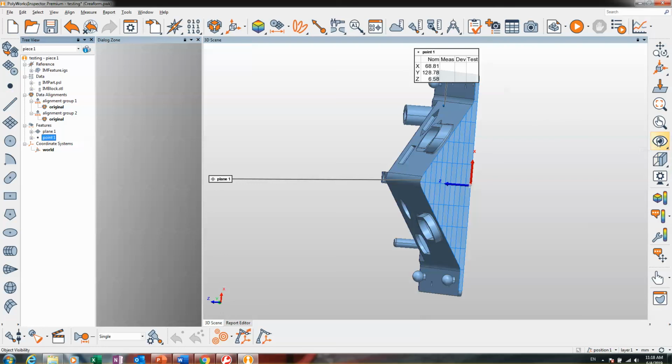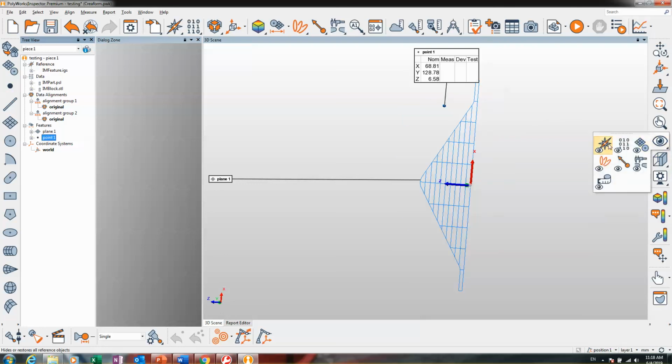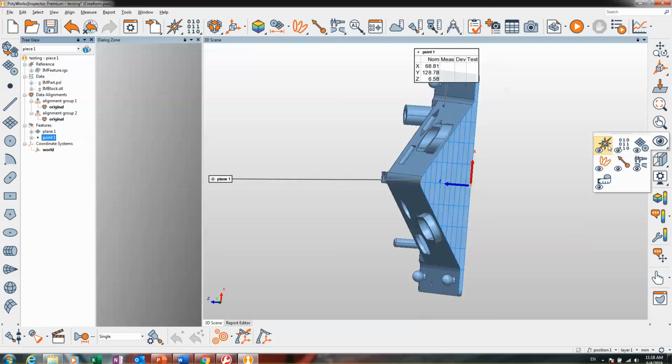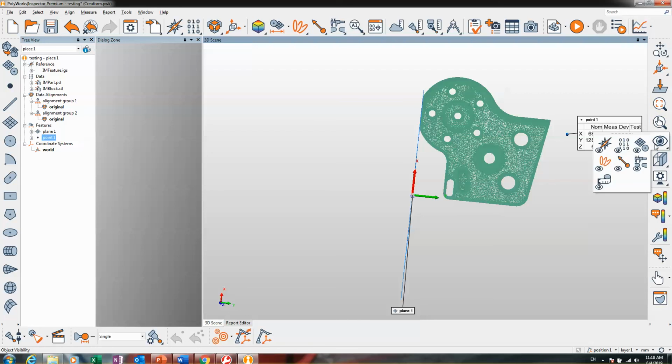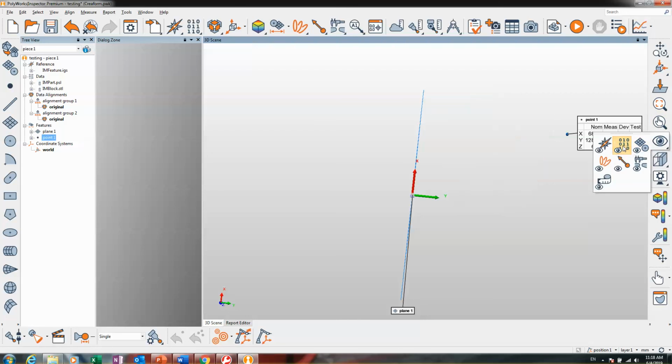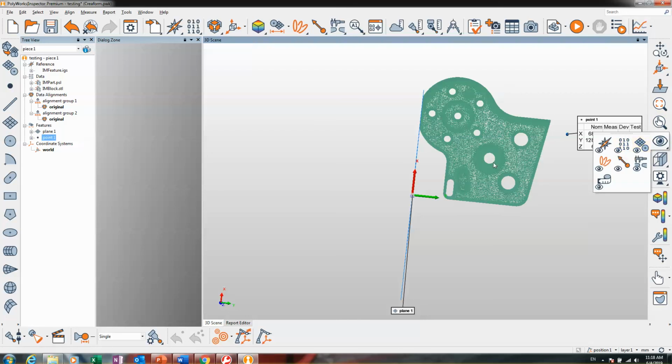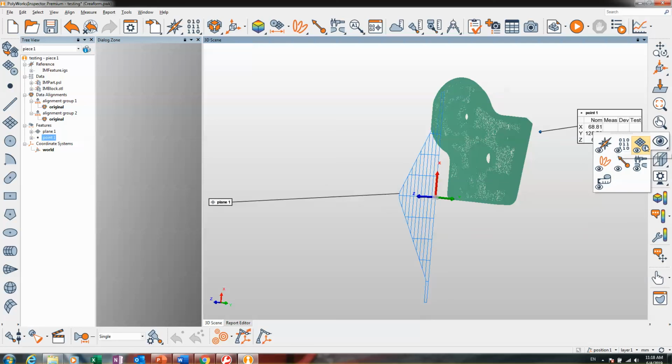Next is about the vision, I mean the visibility. Okay. First one is hide or restore, means hide or show the cap. Click one time to show or one time to hide. This one is data, scan, data probe. See, this is data. This is a hide restore for objects like this. This is a feature. In case you have many features, you click this to hide or show. If you have a cross section, also the same. This one is for hide or show in one time.